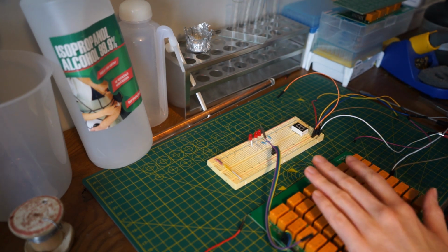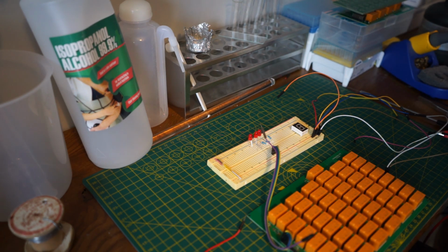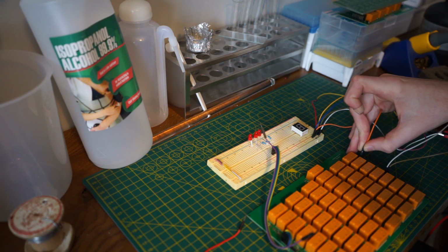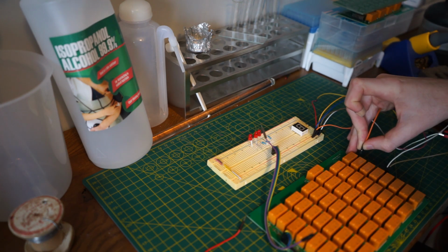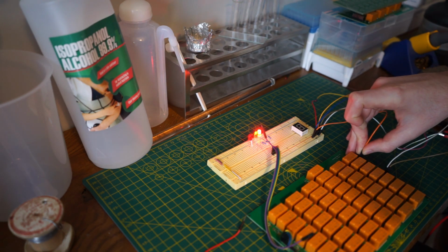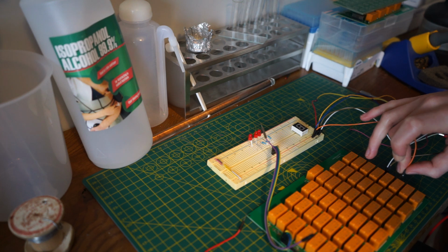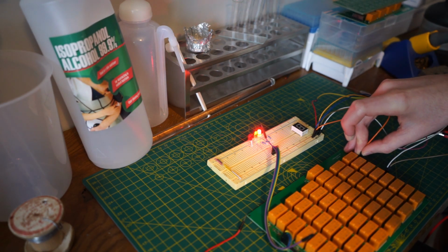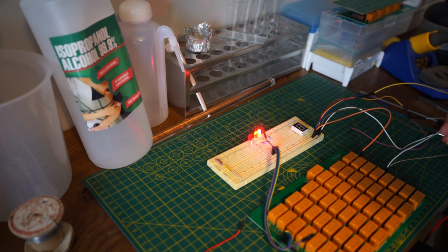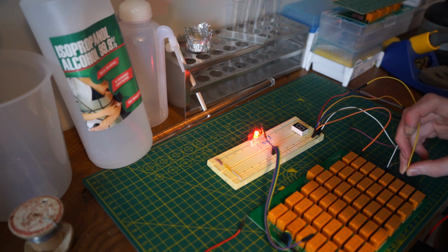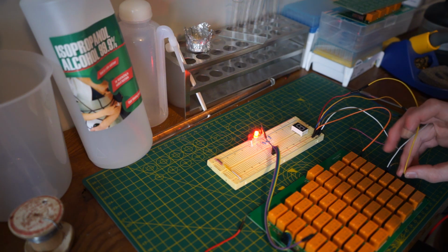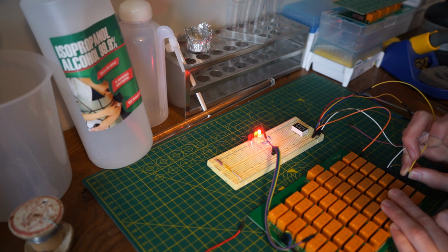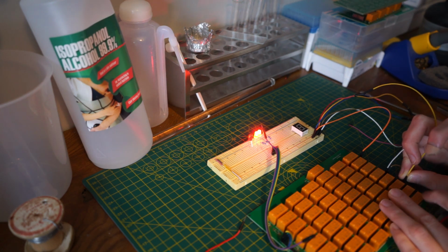So this is the adder board, which I'll be testing now. So if I put a 1 into input A, we should see a 1 on the LED, which is here. And we see that. And we should get the same on input B. Yeah. If I put a 1 on input A and a 1 on input B, we should get 2. Which we do get. And then 1 plus 2 should give us 3. So if I put a... yeah, there we are, get 3.